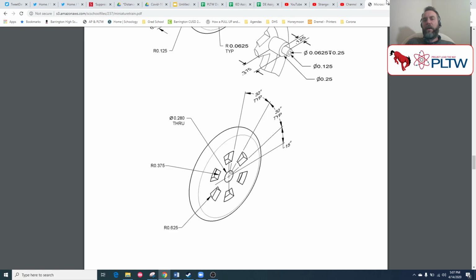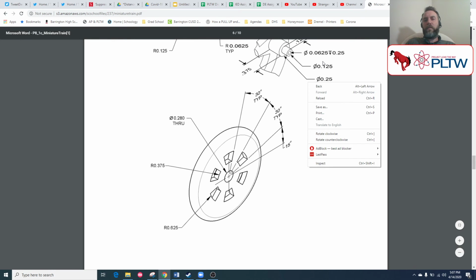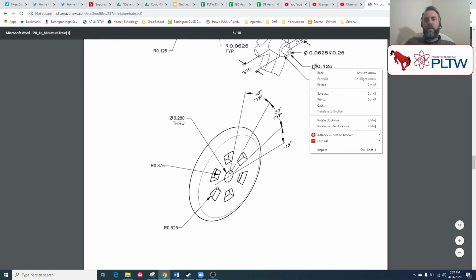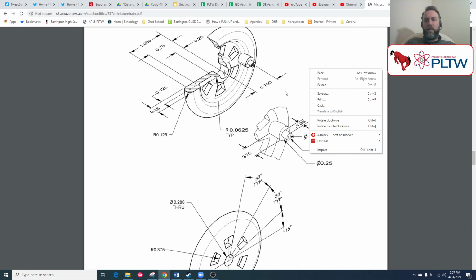Last thing is we've got a series of just circles that we're going to draw. You know what? I'm not going to show you that. I think you guys can handle that. There's one circle extrusion, get it to the correct spot. There is another circle extrusion concentric with that, and then there's a hole concentric with that right there.